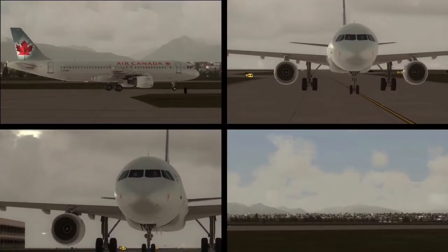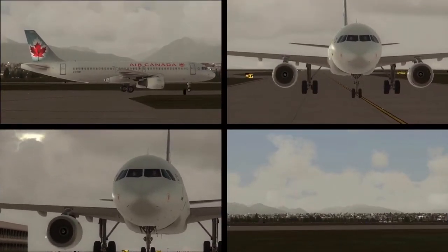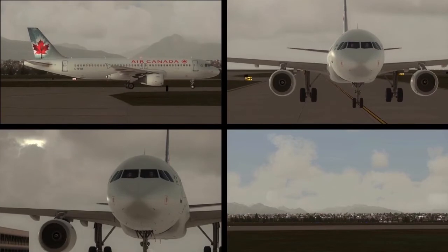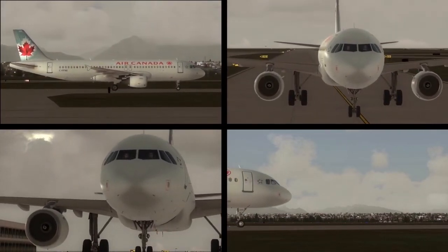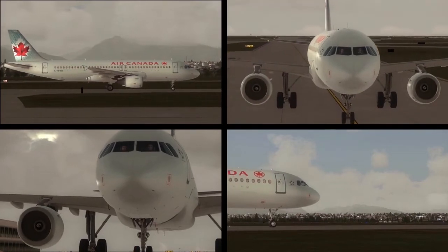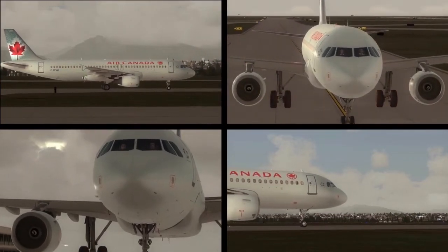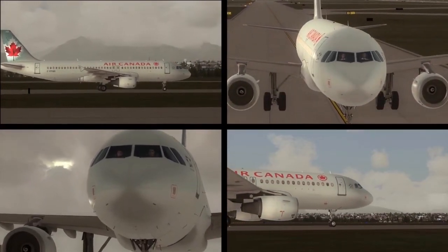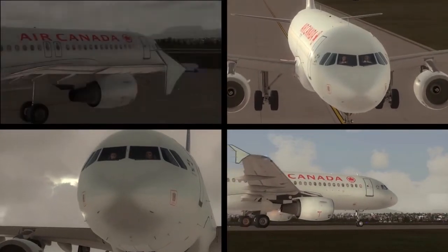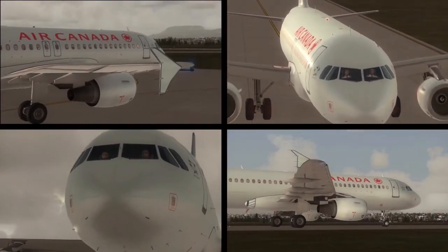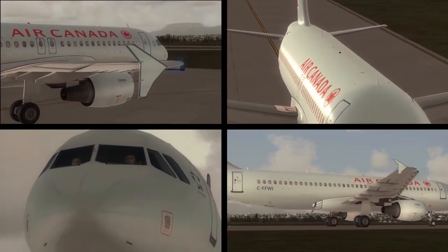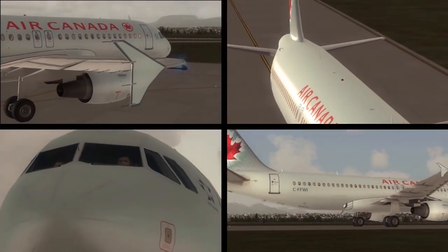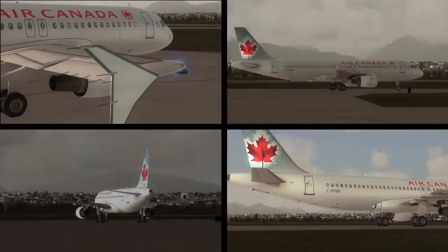We're going to deviate a little here and talk about the A320 family briefly, which has a very loud and conspicuous PTU. If you've ever flown on an A320 family aircraft, you've likely heard the PTU in action. The A320 has 3 hydraulic systems, and the PTU is used to even out pressure differential between the green and the yellow systems. It plays a much more important role on the A320, and runs more often as a result.